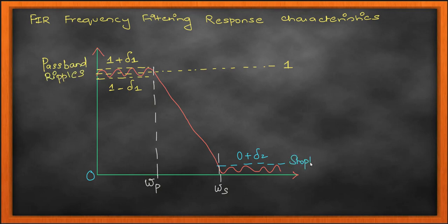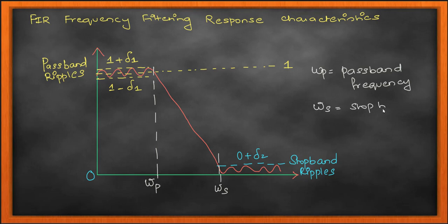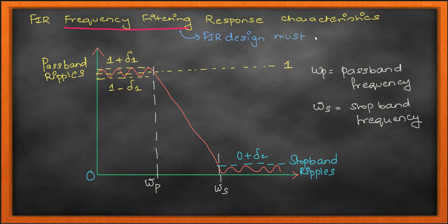What happens is, whenever you go from a high to low, it is like jumping. You want to jump from the top of a floor to the next floor, or to the bottom floor. What happens is, you have to just gear up. You have to accelerate a little bit, and that acceleration is going to come as a passband ripple, and then you jump, and you're not going to go straight because of the acceleration and the ripple. You're going to go in a slanting manner, and then you land, and when you land, you're still not going to follow through with that landing, and that's going to produce these stop band ripples. So this is a perfect example.